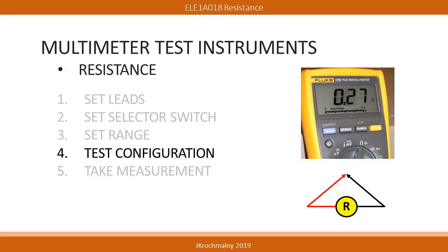At this point, we want to test the configuration of the multimeter to read resistance. When the meter is configured to read resistance, the meter's internal battery is used and supplies the power for the measurement. If the leads are placed together as shown, the meter will display a very low value, perhaps 0.0 ohms of resistance, indicating it is configured properly. If the meter displays OL when the leads are placed together, the meter needs to be serviced by perhaps replacing the internal fuse of the meter.